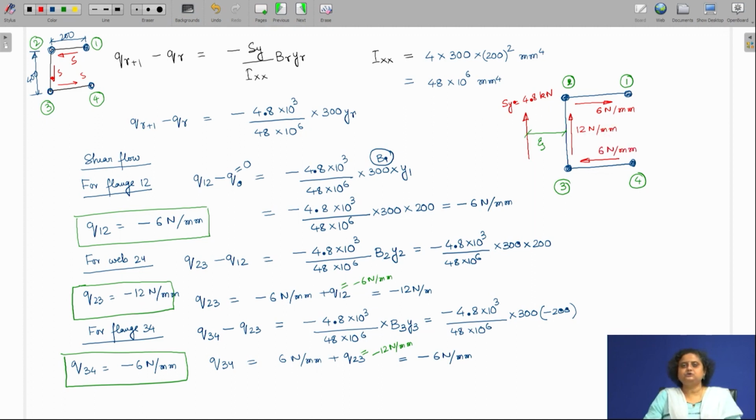So this is the shear flow that we are going to have, and as you can see, the shear flow is constant in any portion between two booms. Now let us see a big advantage of using skin stringer idealization. In a regular thin wall beam, to obtain the shear flow, we have to perform an integration, as you have seen in the previous lecture.